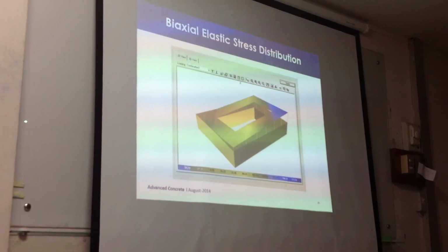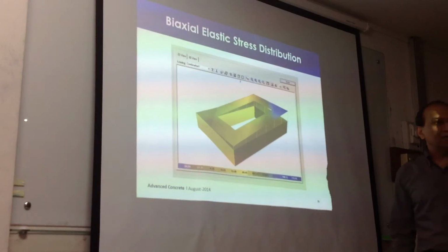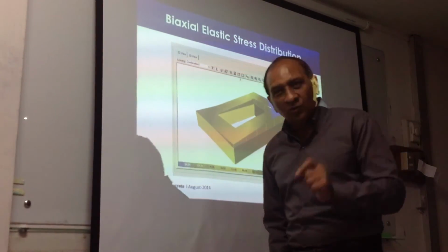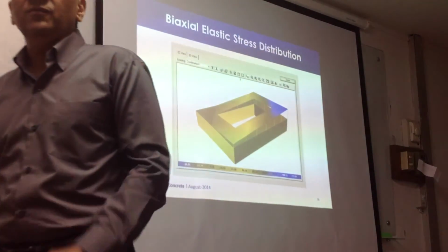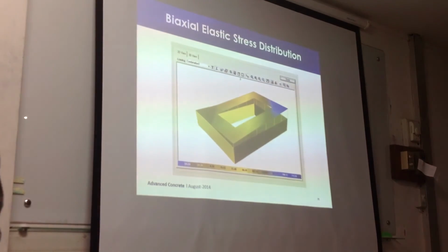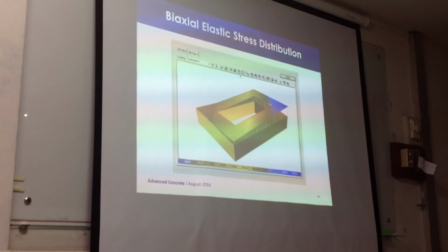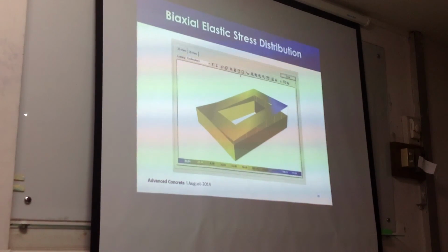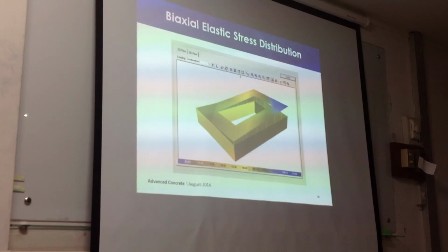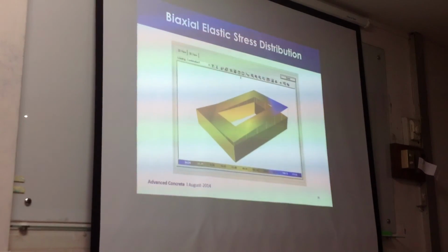But just for our convenience, we assume the strain to be equal to 0.003 always, irrespective of the moment value. Correct? So that condition of 0.003 strain never ever happens. But still, that is the basis of our design in the codes.